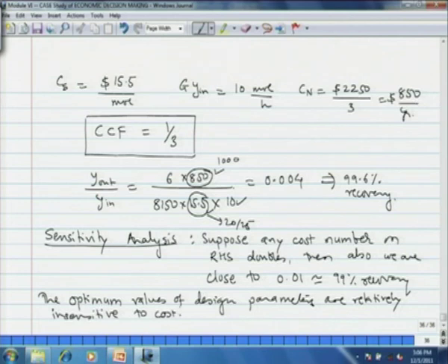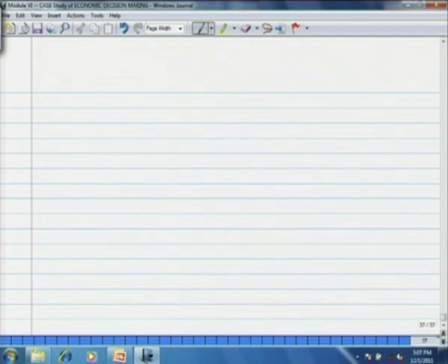Or in other words, the total cost of operation of the process is relatively insensitive to the design parameter. Okay. And this is a characteristic of a large number of design problems, that solutions are often very insensitive to the physical property data or the functional form of design equation or the design parameters such as heat transfer coefficient, cost data, etc. Therefore, good engineering judgment requires that we obtain some idea of the sensitivity of the solution before we go further with the analysis, with the design.